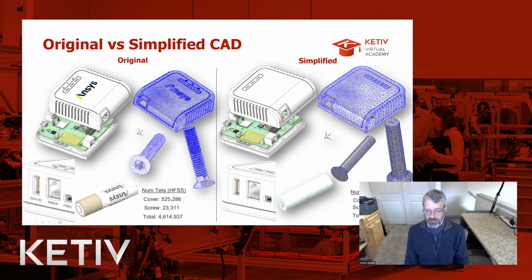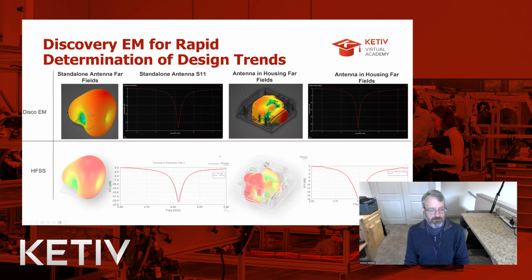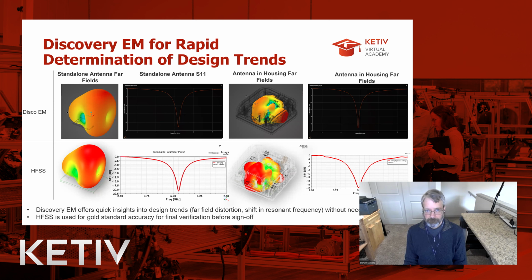And Discovery makes that kind of simplification very easy and sort of what it was designed for. And so with that, we can get far field patterns, compare them with and without a housing, and again, get a good feel of what's going on. And you can sort of see how the initial results are pretty darn close, but not precise. And then do a finalized run within HFSS. But this allows us to do sort of rapid determination of design trends much more quickly, which can be helpful as you're designing.